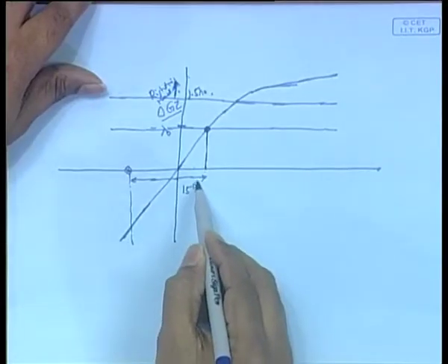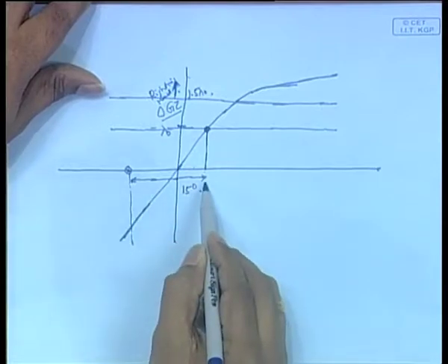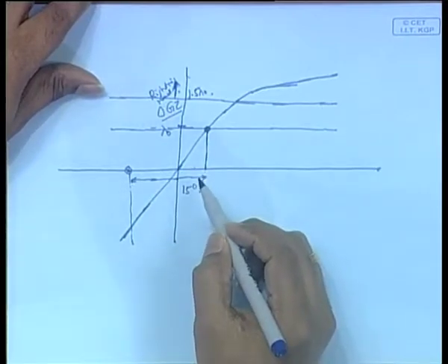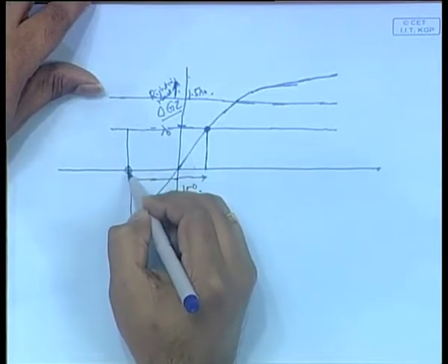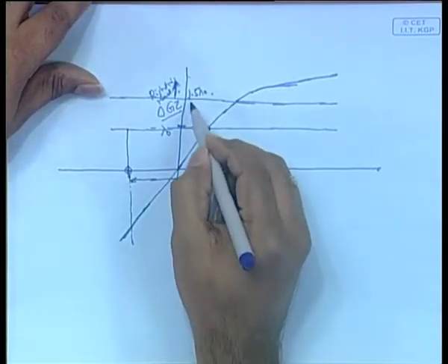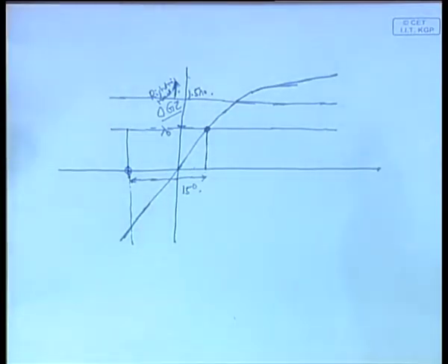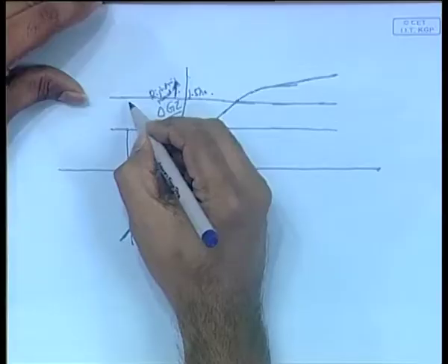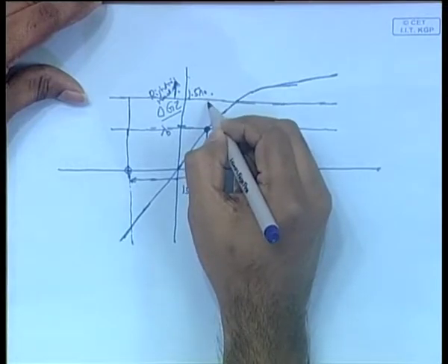So, we assume that it has tilted up to 15 degrees. So, from here it has tilted up to this. Now, what we can do is, we are just going to provide a safety factor. There is no logic to it except that it is for safety only. If you assume that x is the amount of energy that the wind has given to the ship, let us assume that 1.5x is given, just to make sure that in case there is some other error somewhere, we have taken care of all that. So, you make it 1.5x. That is the meaning of this.